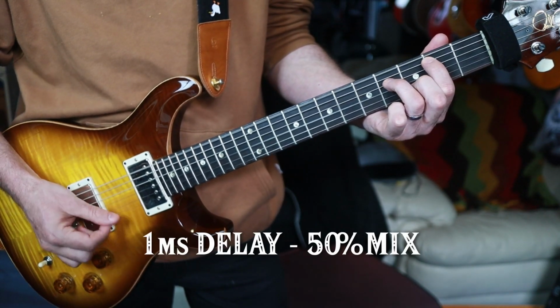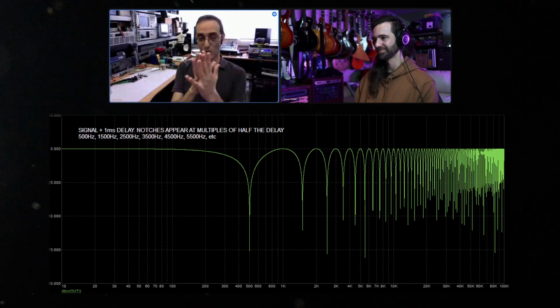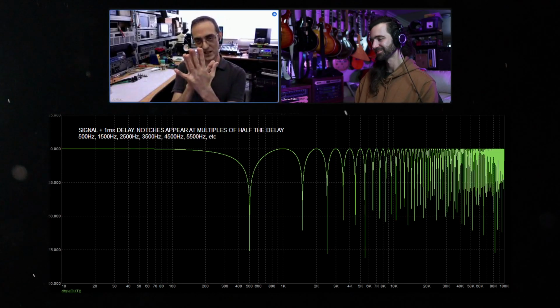So that's what happens when the signals are so close together. The delay is so short that some parts will really combine, some parts will really eliminate. It's not that it's impossible with a long delay, but the signal is different over time. So even if the note is the same, the signal is slightly different. If it's so short, you are comparing the signal to itself, just slightly off.